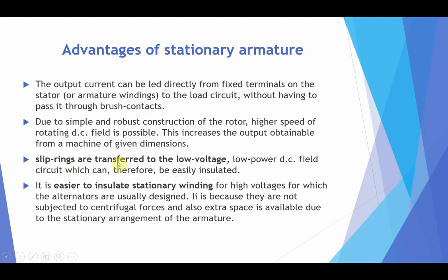Slip rings are transferred to the low voltage, low power DC field circuit, which can therefore be easily insulated. It is easier to insulate stationary winding for high voltage, for which the alternators are usually designed. It is because they are not subjected to centrifugal force, and also extra space is available due to the stationary arrangement of armature.